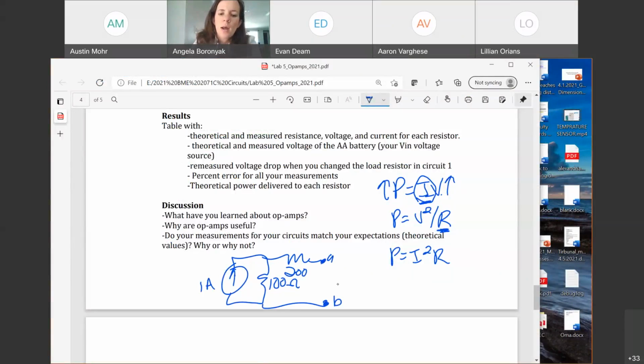Good, a wire. And I'm looking for the current that goes in that wire from A to B. Like when I did Thevenin voltage, I was looking for the voltage at A positive to B. Do keep in mind the sign for that can matter. So I want to know that current. How can I find that current that goes from A to B? That will be my Norton equivalent current.